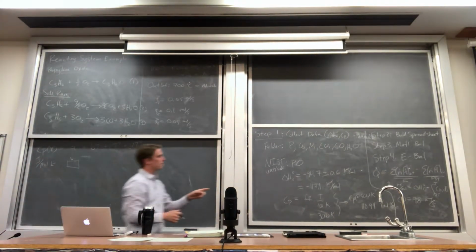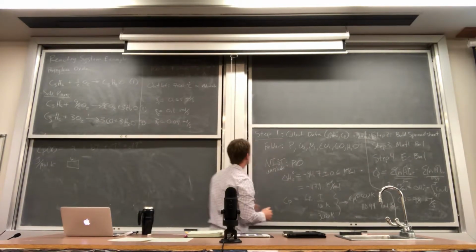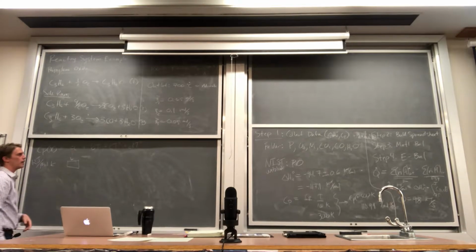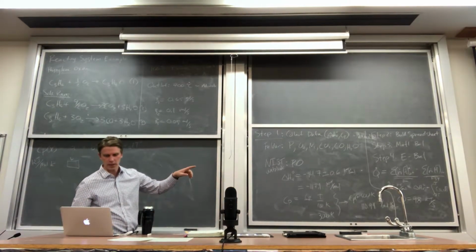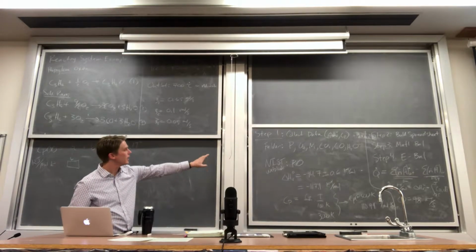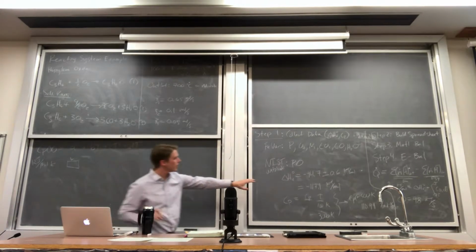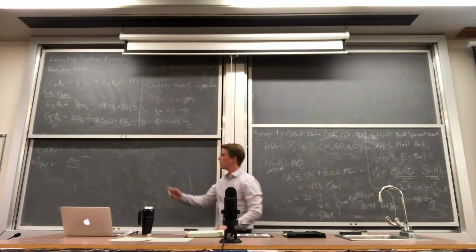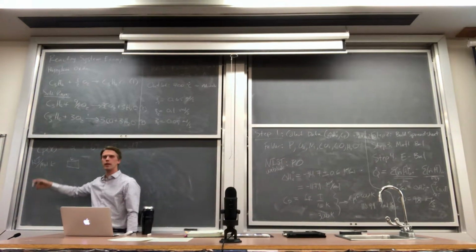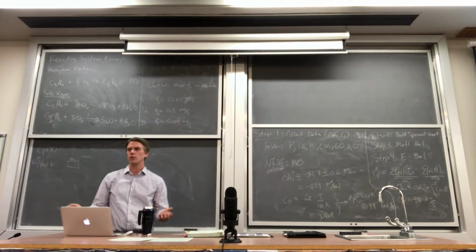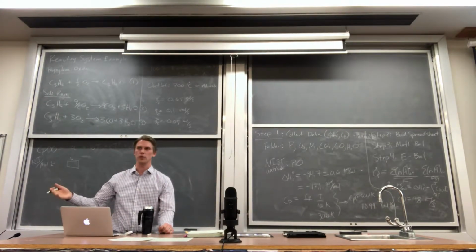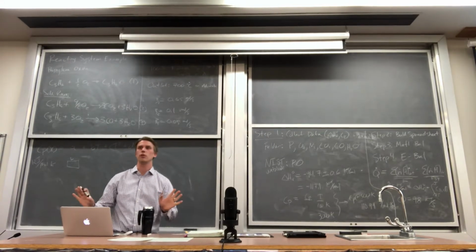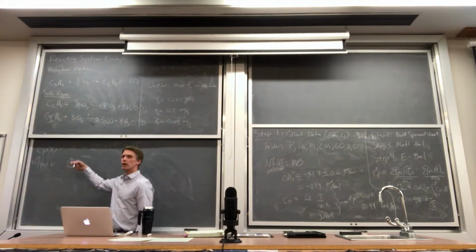And in this case here, I believe the correlations in the back of the book are actually kilojoules per mole Kelvin. And so when I entered it into the spreadsheet here, where is the number here? Yeah, 110.99 joules per mole Kelvin. So the correlation in the back of the book is kilojoules per mole Kelvin, but it's times 10 to the minus 3, which the units all work out then. It would be 0.1 kilojoules per mole Kelvin or 110 joules per mole Kelvin. So just make sure the units work out. But that's a little trick that I threw in there to modify this.